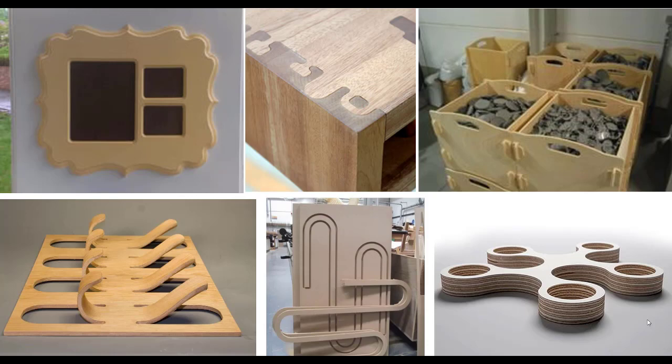So I'm pretty sure at this point, just by being around the college, you've seen the CNC, more than likely seen it in operation at some point. The CNC is effectively a computer-guided router cutter, and within AlphaCam we can draw any shape or any curve or any piece of geometry we like, and then we can apply a toolpath or send the cutter, the router cutter, along that path. So it's a relatively simplistic procedure in practice. It's actually quite complicated if you were to code it manually, but we're not going to code it manually. We're going to use a software called AlphaCam to visually draw and sketch the shapes we want processed, and just more or less drag and drop on the cutters, and it'll automatically generate the complex NC code, the programming, from our visual CAD package really.